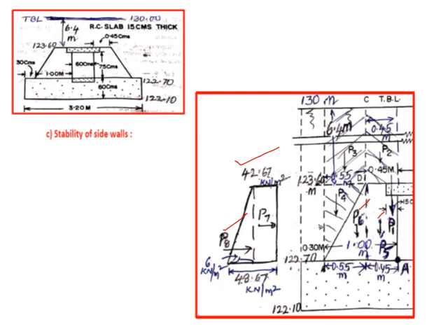Then what is the lever arm for P4? You can come down till here, which is 1 meter. So you can deduct this portion, 1 minus 0.55 by 3, or you can take 0.45 plus 2/3 of 0.55. So what is lever arm for P7? P7 is this, half of 0.9. What is lever arm for P8? It is one third of 0.9.